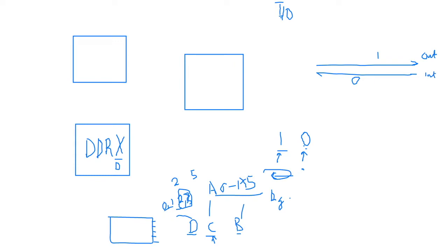Now we remember that the data direction register is a port, so it means this is 8-bit wide. Which means as you look at the ATmega chip, as we saw earlier, you have these pins, and these pins can be 0 to 7, for example. And then we have picked pin 2, which is actually the 3rd pin, and we have assigned this.